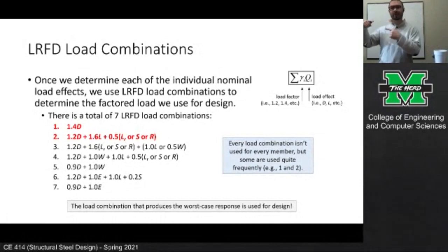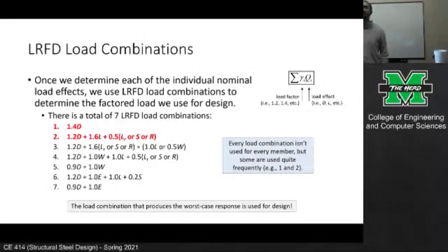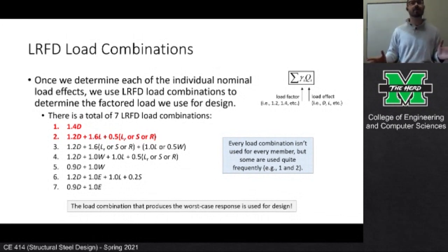So its actual less stable state might be while it's being built. I saw a comment. Yeah, it's why you have to use shoring during concrete. You know, you shore up the flooring system, and shoring versus unshored construction is a big thing in structural engineering because shoring can be expensive, and it's a big trade-off.